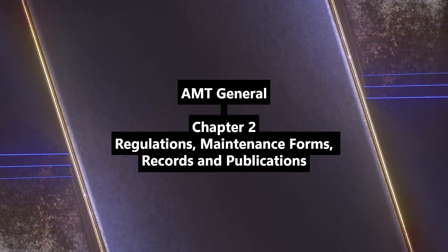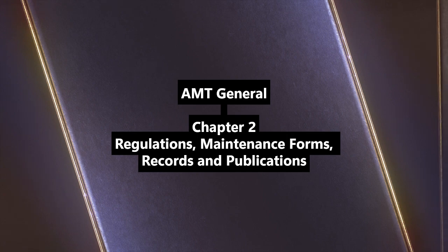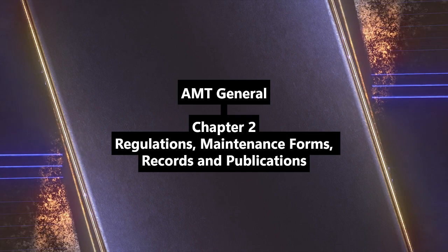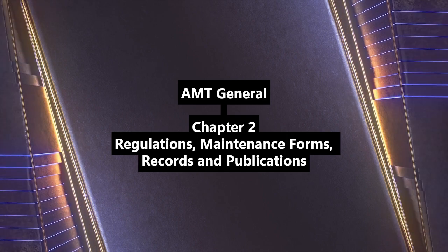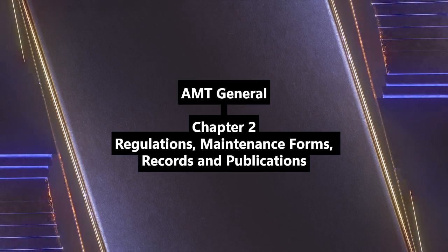And of course, manufacturers publish data. The absolute primary source. OEM data is king. Part 21.50 requires ICAs, instructions for continued airworthiness, be provided with new products, STCs. And those ICAs have to be comprehensive.